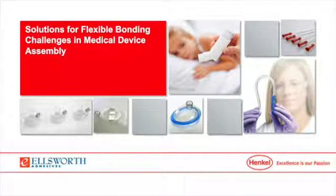Thanks, Molly. Okay, and Christine, we're going to come to you on this one. How can I best determine adhesive cure? Another common question we often get, especially as adhesive suppliers like Henkel and Ellsworth. In most cases, we suggest, and this is what most of our clients typically do as well, some sort of physical test. That physical test could be something bond strength related, it could be a hardness test, et cetera.